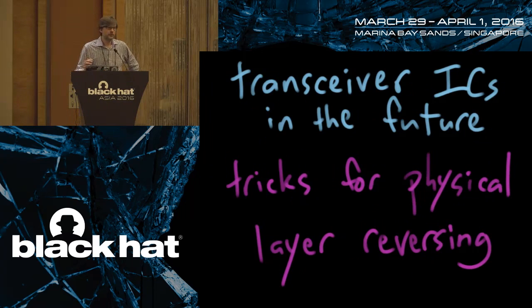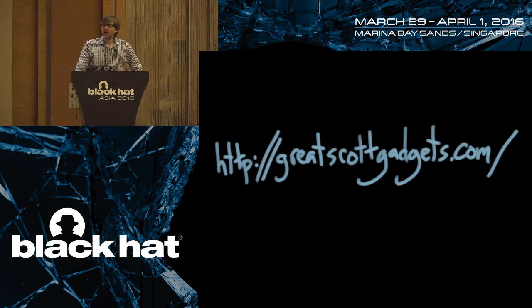But we might also have better tools for reverse engineering just using the transceiver ICs in the future. In particular, I've talked with some folks about some tricks we could use with things like the YARD Stick One to reverse engineer the modulation and the data rate. But primarily those tricks are things like: try a whole bunch of different modulations and see what works, try a bunch of frequencies and see what works, try a bunch of data rates and see what works, or oversample and then figure out what the periodicity is and stuff like that. It's kind of hackish. And so in the long run, I think SDR will win.